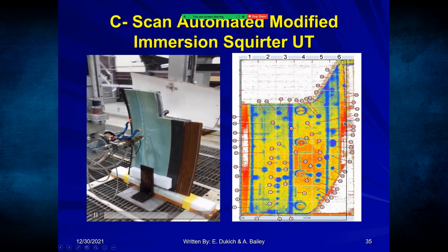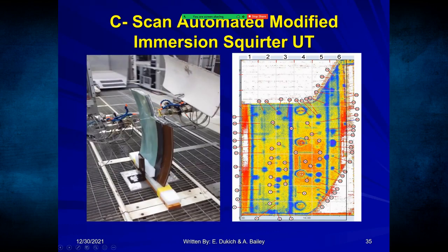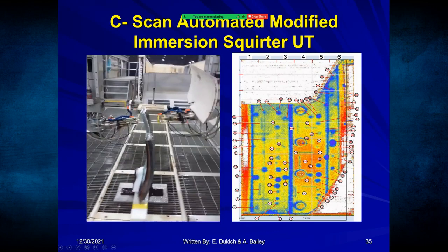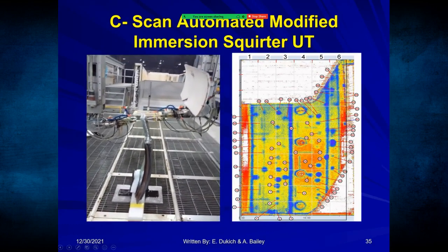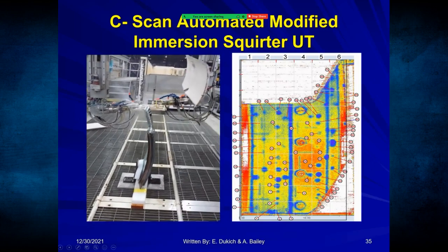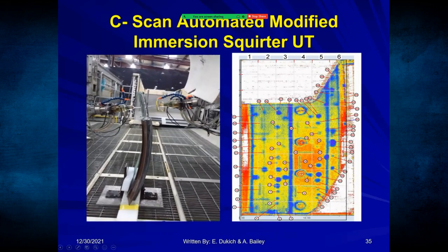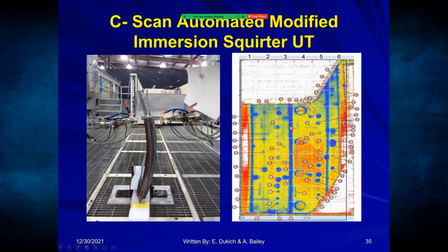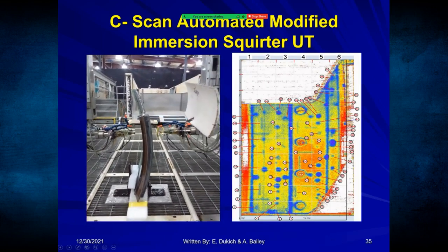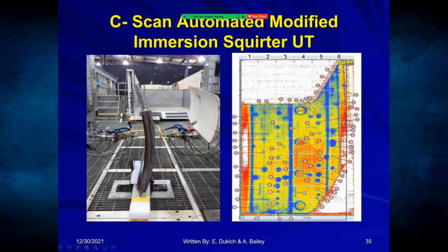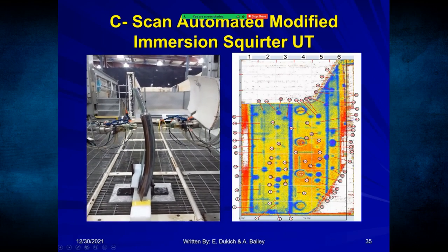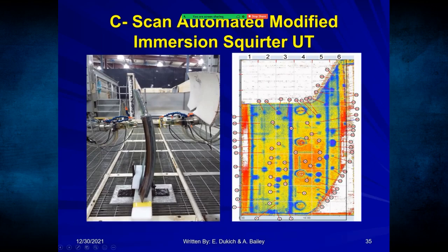So over here to the right, if you can see my mouse, we can find up to 70 different indications that are manufactured. All of these blue dots right here represent a possible flaw. So I have to calibrate this machine to detect all of these flaws at different layers, different depths, different sizes, different designs. These are all the flaws that the manufacturer requires us to find.